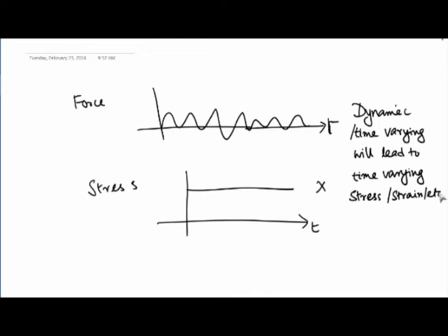The problem in the analysis of dynamic stresses and dynamic strain is that, from your theories of failure and design of machine elements course, you would have come to know by now that if the material is subjected to fluctuating stresses, then the critical limit, which is the endurance limit in this case, is much lower.